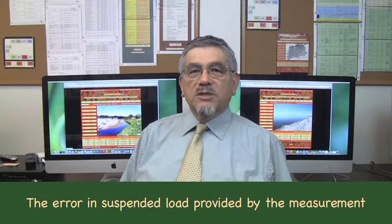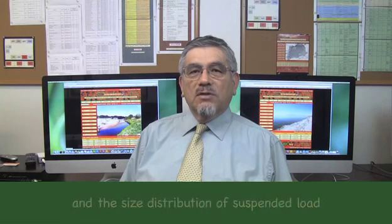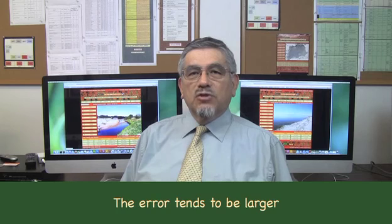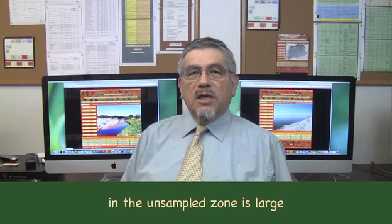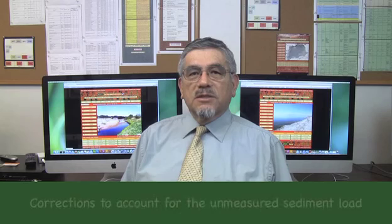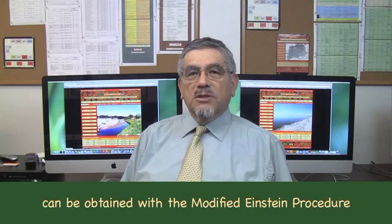The error in suspended load provided by the measurement varies with the depth of the unsampled zone and the size distribution of suspended load. The error tends to be larger where the vertical concentration gradient in the unsampled zone is large, that is, for the coarse sand sizes. Corrections to account for the unmeasured sediment load can be obtained with methods such as the modified Einstein procedure.